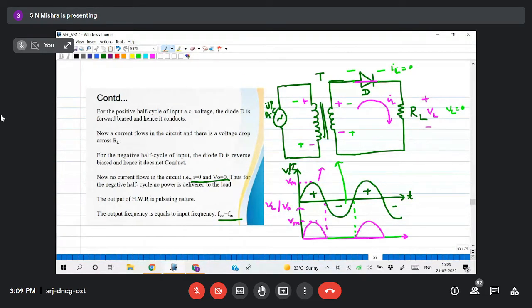So in that process what happened, I'm getting positive half cycle and negative half cycle is clipped or cut. So this alternating nature is now converted to direct current or direct signal. Though it is not perfect, because perfect means it is constant throughout the time, it is somewhat unidirectional. Okay, so that thing we have discussed.